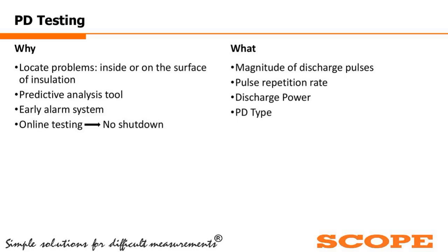It could be one set of measurements in the morning, one set in the afternoon, and one set in the evening, to get different load profiles and different temperature profiles, because nobody has made any conclusion throughout the globe about when PD will be generated. People are talking about whether PD is at the highest voltage level or at the highest current level, or what the scenario is, but nobody can say. So you have to look at different times.